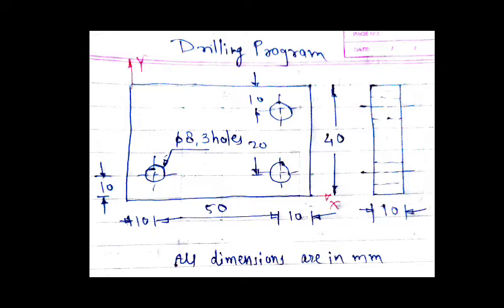As we have seen before this lecture, we made the part program and we gave the sequence numbers, that is N0050. We have seen N010, N015. We maintained a gap of either 5 or 10. Why? If some modification is required, then we can insert a sequence number in between the present blocks. We assign an in-between number to the modified block, so we can insert that modified block into the program.